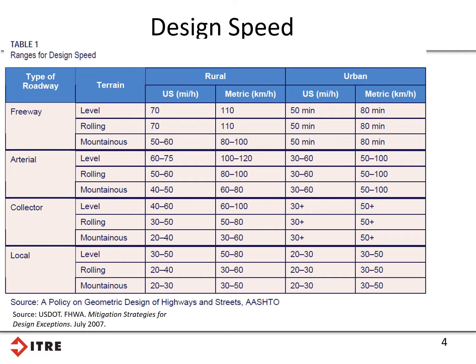The inferred design speed is from the driver perspective. As a driver drives along, what design speed is getting communicated to them? How do they understand the roadway? That's highly related to the operating speeds, the speeds that vehicles are actually driving on the roadway.